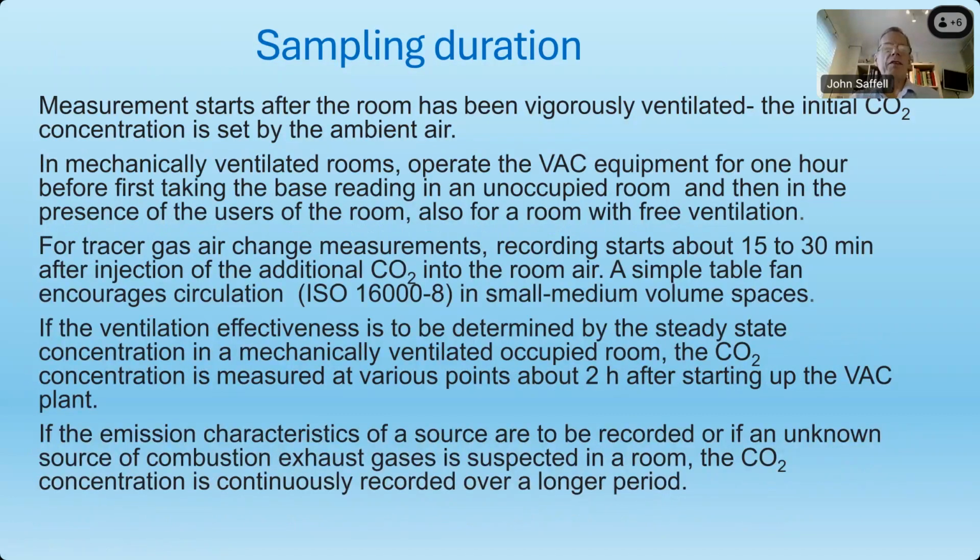How long do you ventilate? Well, basically, your measurements start after the room has been ventilated. If you're going to do an ideal measurement, you'll wait till the room has been vigorously ventilated until the concentration is set at ambient air. That's your baseline. And then you proceed to have people come into the room or something. And this is an ideal situation, which you cannot achieve normally, as Mark was saying, that you just don't get that steady state that you'd like to have.